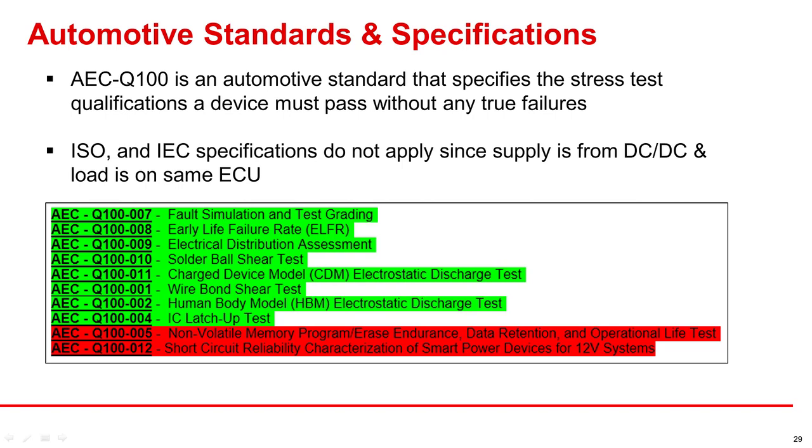Automotive load switches have to go through the AEC-Q100 standard stress test qualifications. You can see some of them at the bottom of the page, along with a few that do not apply, marked in red. ISO and IEC specifications do not apply to load switches, as the input rail comes from a regulated DC to DC converter, and the load is on the same ECU as the load switch.